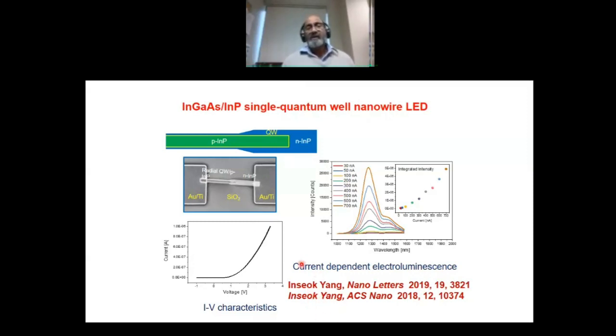He is now at Samsung in Korea. He came from Samsung, did his PhD with us, and went back. So as Professor Shenoy was mentioning about PN junctions, you need to really dope this indium phosphide with a P-type dopant, like zinc, for example. Then he grew this indium gallium arsenide quantum well here, for example, this yellow layer. And then he puts N-type indium phosphide on the top here.